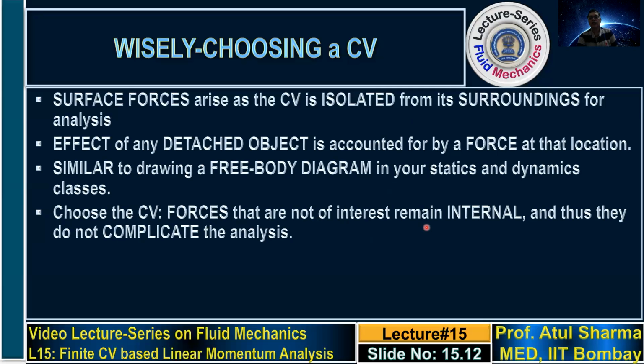Like in the problems that I had presented, flow through a nozzle supported on a tripod, or flow through that tap, we are not interested in the viscous force and the pressure force near the surface. Those are internal forces, as I have mentioned, and they complicate the analysis. So we should avoid these internal forces, which were there in that pink control volume, but not in the black control volume.